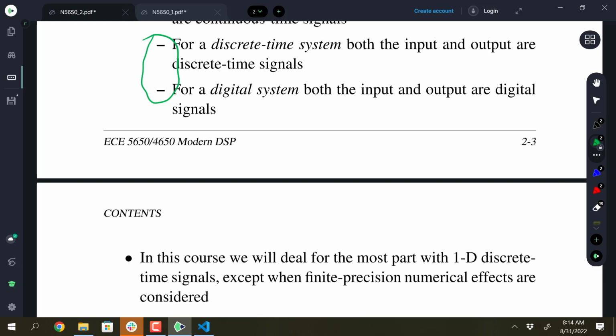I was just thinking about software-defined radios that I have. One of them, the RTL SDR, which was used in the COM lab last spring, only brings in samples at 8 bits. In phase, which is the real part, and quadrature, which is the imaginary part, are just at 8 bits. It seems like, how can you get by with 256 levels of amplitude, which is what you have with 8 bits?